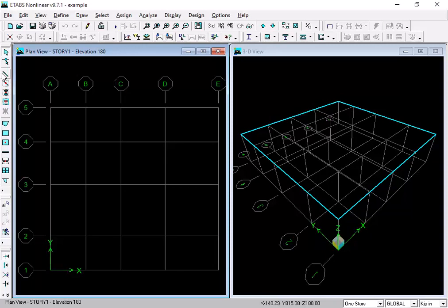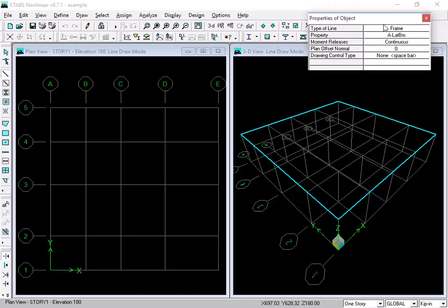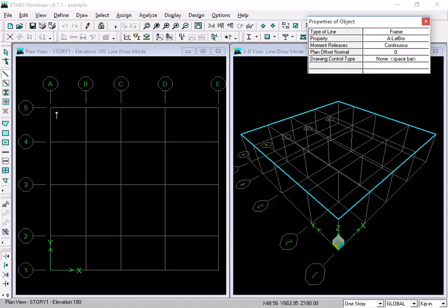Okay, so I will go to the draw mode, ignore this panel right now, and just do sketching. Click here, left click, and click on the other point. This is a beam. You will see your cursor will be attached, and then click here. Just click on the first point and the last point, and you will have lines just on clicks. So we are plotting beams.